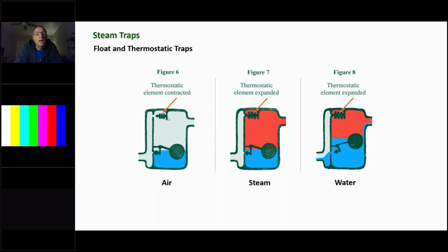So in order to keep that from happening, we put the tank in to collect the condensate, and then we put a control on the boiler called a pump controller that would then activate the pump on the boiler feed tank whenever the boiler is calling for water. So it operates in the same principle as a thermostatic trap. It has a thermostat up top and the float down at the bottom. As the steam enters, it causes the fluid in the element to expand and pushes the pin into the top of the trap, keeping steam in the line as opposed to going down the return line and energizing all of that wet return.